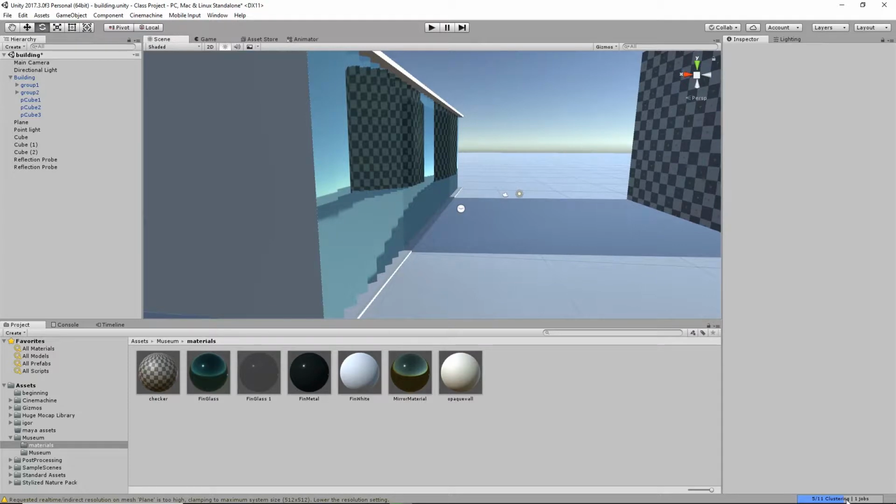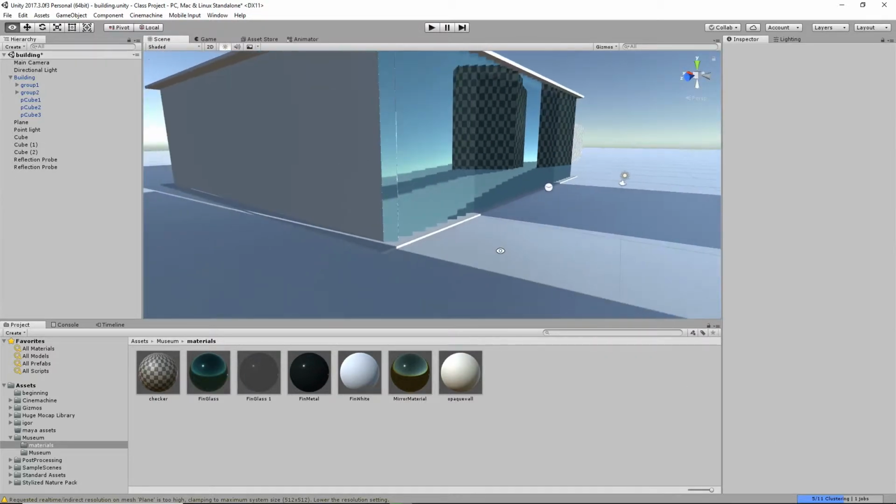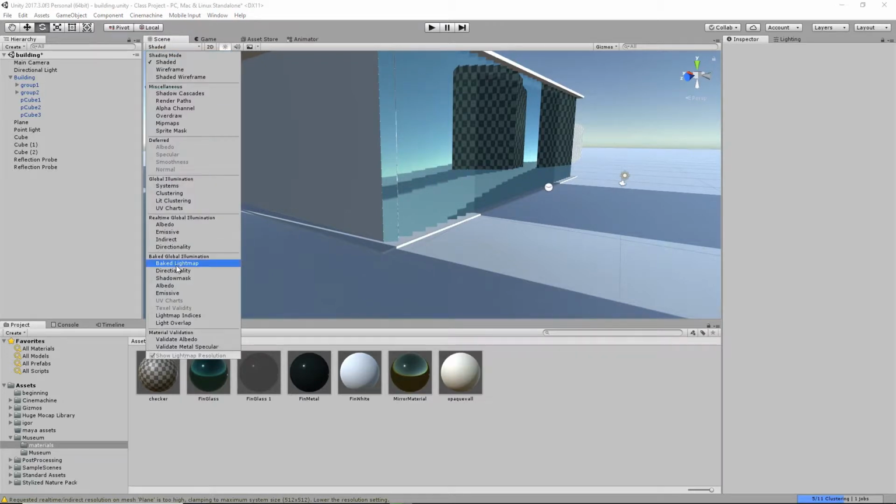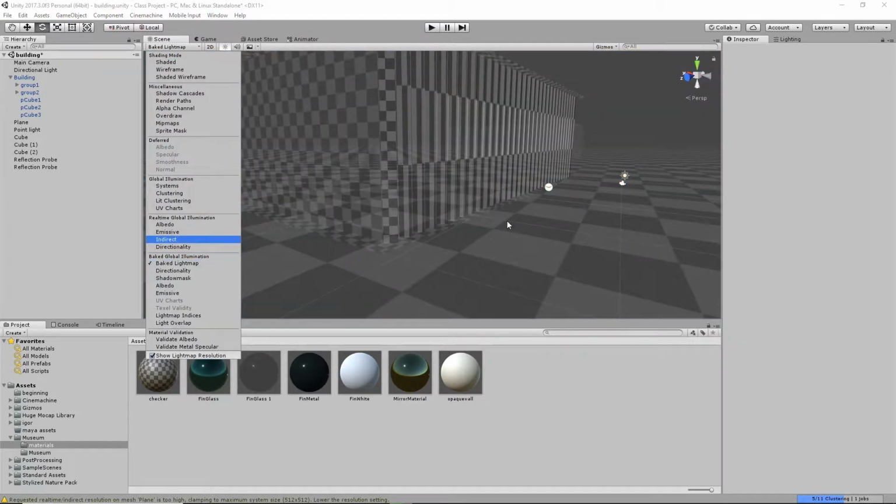So it's still generating the light maps. That'll tell you why you have to do what I showed you, trying to crank these light map densities down and get your UV maps on your objects correct, so that you're actually getting some finite light maps for those.